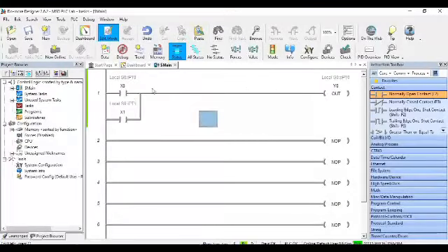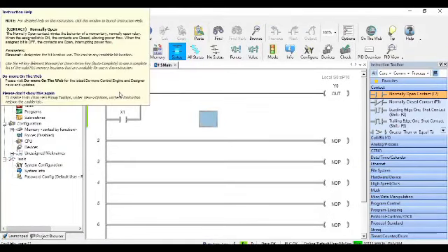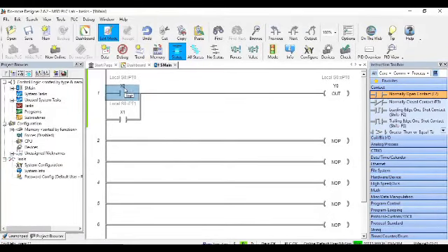You can do many things by just knowing basic logic. So let's say you have a bulb over here and you have two different switches across your house. If you wire x0 and x1 like this to a PLC, then you can simply write this programming ladder logic to complete that task.